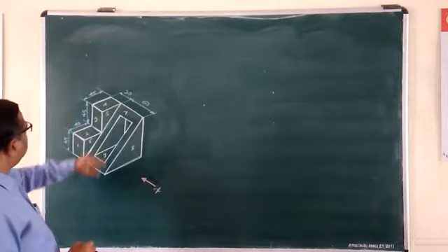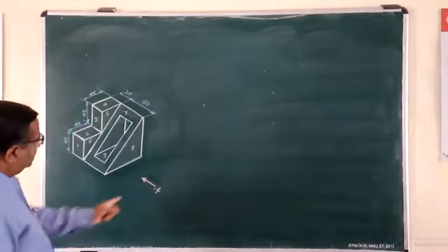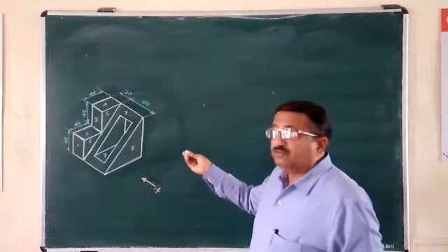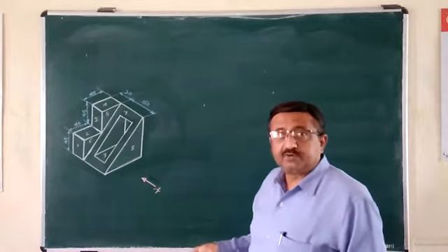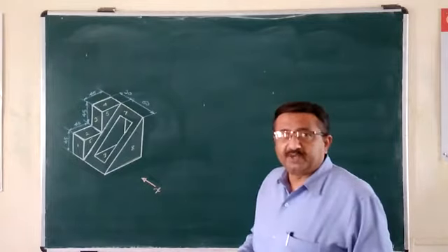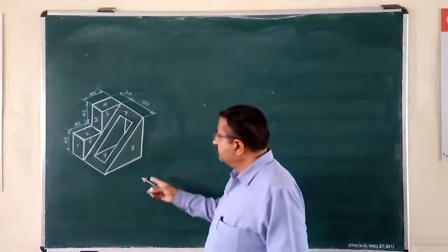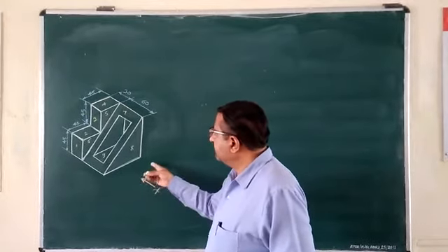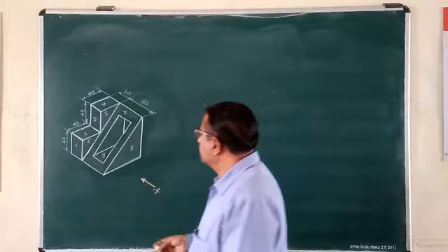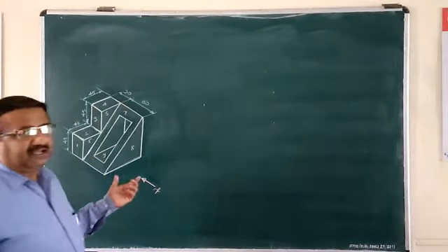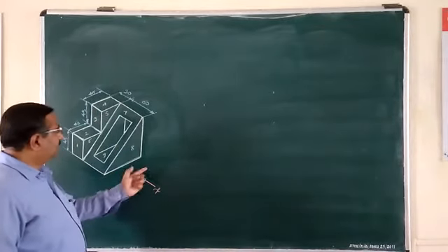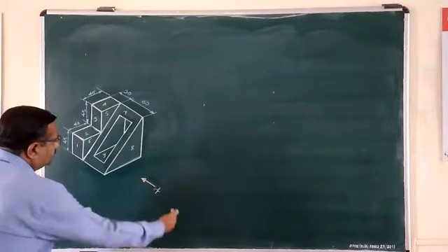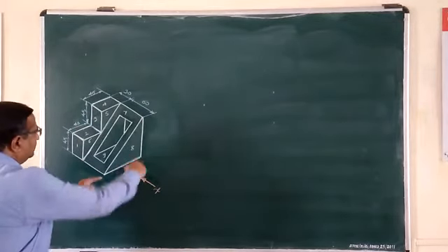Okay, all the dimensions are also well mentioned. In the direction of x, we have to construct its first orthographic view, which is nothing but its front view. So in the direction of x, naturally, what are the parameters? It will be length and height. In segments, only length is mentioned. Instead of giving one overall value, 2 segments are used here. See here, in the direction of x, the front view shows length and height.